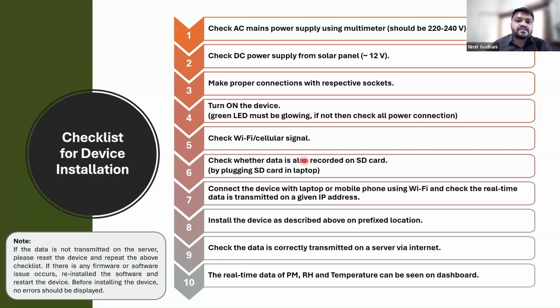Yeah, the first two questions I will answer, and I have also added the part on drift and others later in this lecture. Regarding the sensor, it won't be possible to keep a constant temperature inside the box. So what we mostly do is put it in the shadow of the solar panel or somewhere that has a minimum effect of temperature.